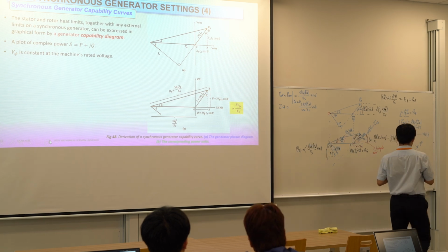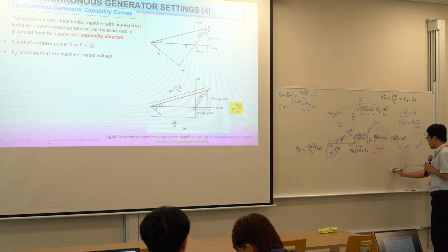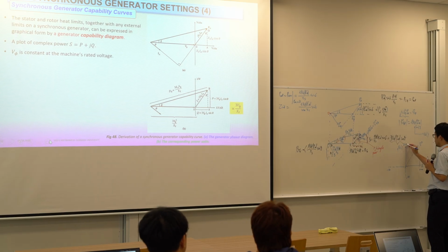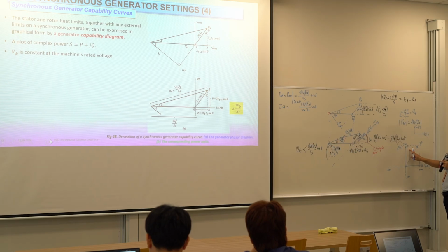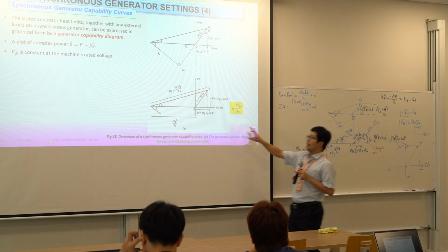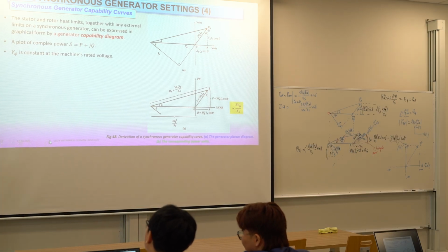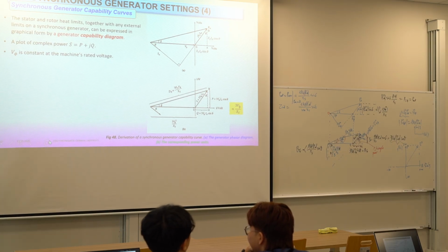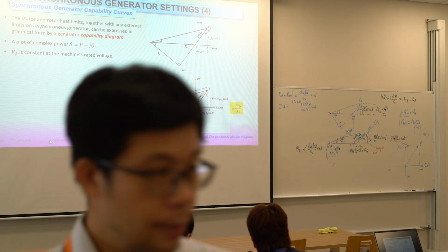And look, if we follow the arrows, this is minus infinity to positive infinity. So Q is positive, P is positive. That means this is the lagging case. We assumed before that in the lagging case PG is positive, QG is positive also. Is it clear? Any questions?